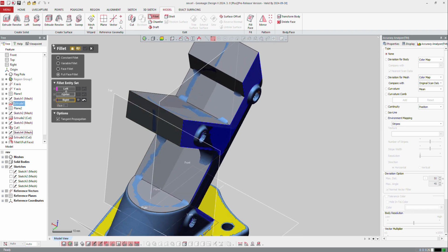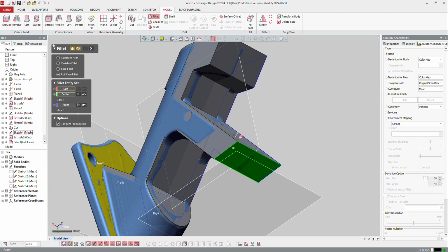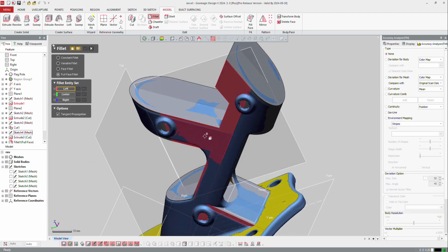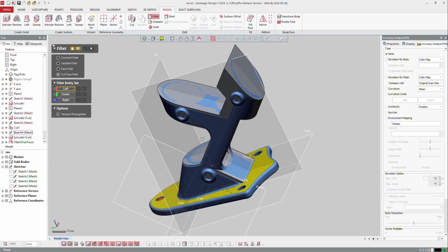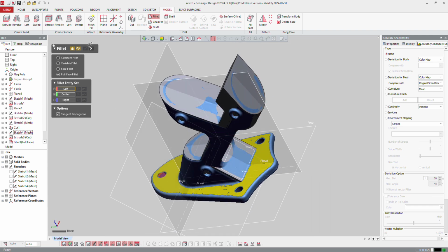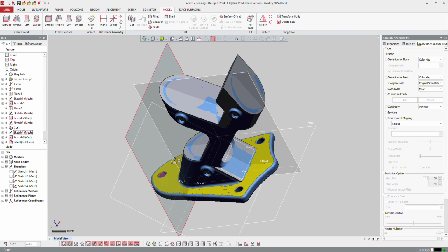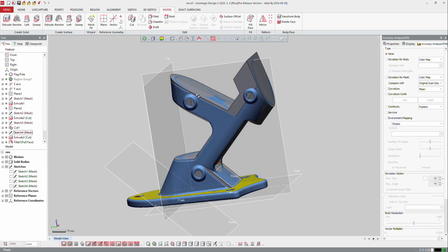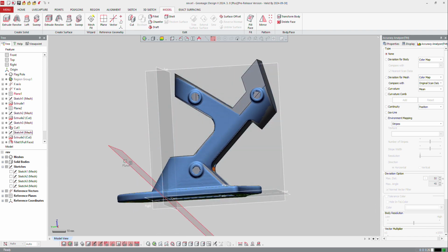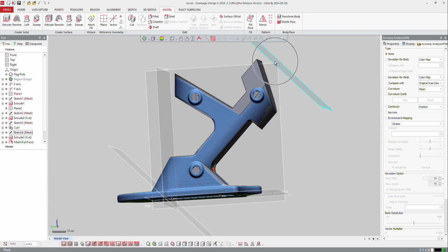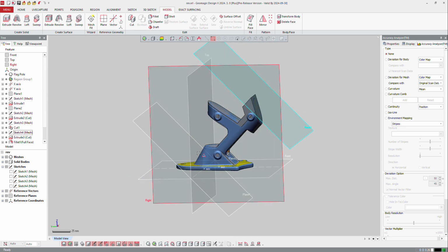Okay, let's make the same thing over here. So left or right, center and left, and make a tritangent fillet. I cannot do that here because if I do it here, it's going to be really awful. So instead of doing that, I will leave that and I will use sketches. From that plane here, I want to make another plane parallel to that one over here. So I will just press Control, click and move the plane to have an offset plane of that one.